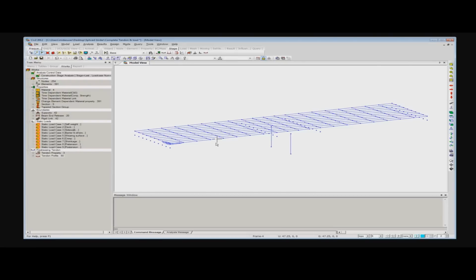We applied the loads, and now the next step is going to be moving loads: how to define the moving load, how to define the vehicles, select the codes, and define my lanes, number of lanes, and all this stuff. For that reason, I'm going to the moving tab, pressing on this vehicle here. It asks me for a code, so I have the option to select from a variety of codes which I have here. Now we go with the HL-93 LRFD.